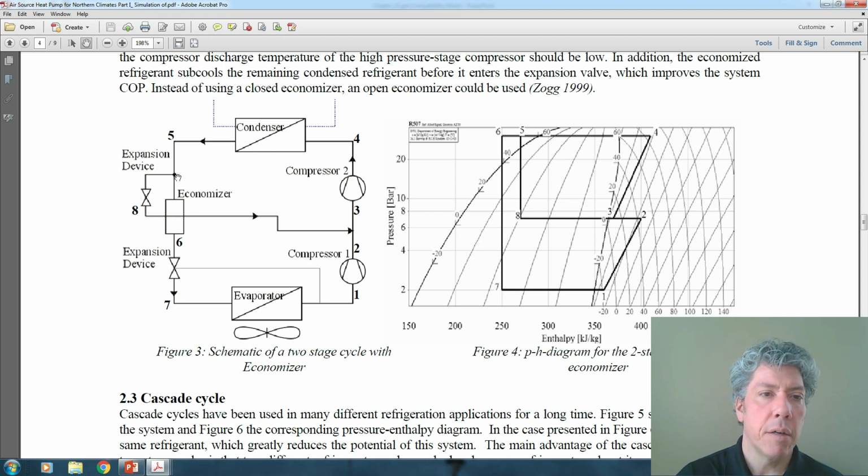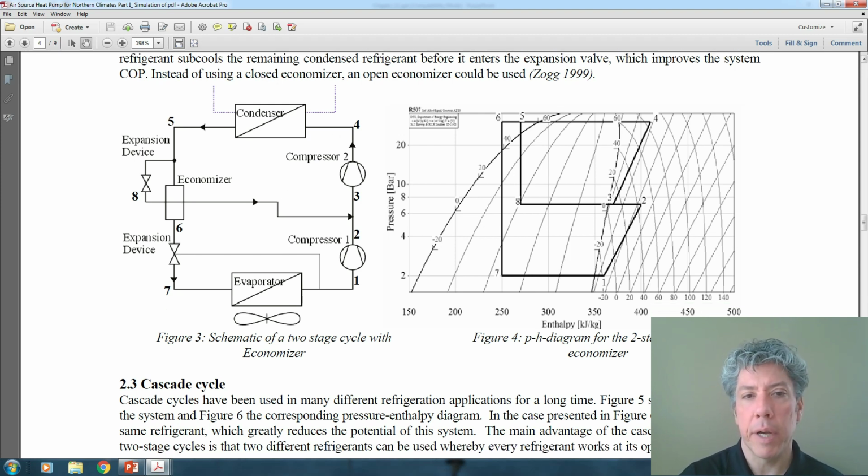But now you've got refrigerant that hasn't expanded yet. It's still at full pressure, but it's cooler. And so when it expands, it really drops to a very low temperature. So they're generating a very low temperature for the sake of operating this in a cold climate. You know, if the temperature outside is negative 20 degrees, then you've got to have refrigerant much colder than that, say negative 30 degrees, for it to pick up heat from the outdoors and be useful for putting indoors. So before it goes to the outdoor evaporator, it's cooled down and then expanded, so it's very cold, to then pick up heat and go into the compressor. So this is a particularly interesting cycle, and I hope you'll recognize it again in a moment.